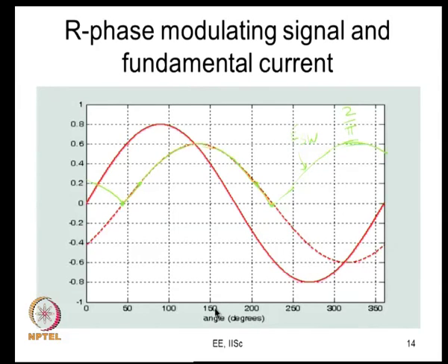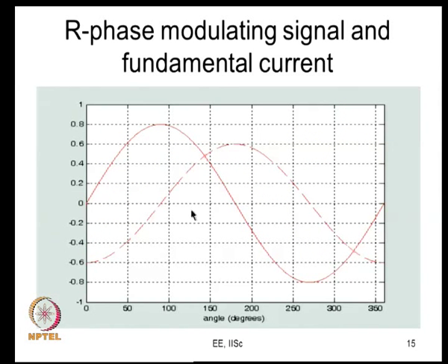Therefore, the switching energy loss depends upon the amplitude of the load current. It is independent of the load power factor for continuous PWM methods, and it does not change significantly from one continuous PWM method, say sine triangle PWM, to another continuous PWM method, say third harmonic injection or conventional space vector PWM method, right.